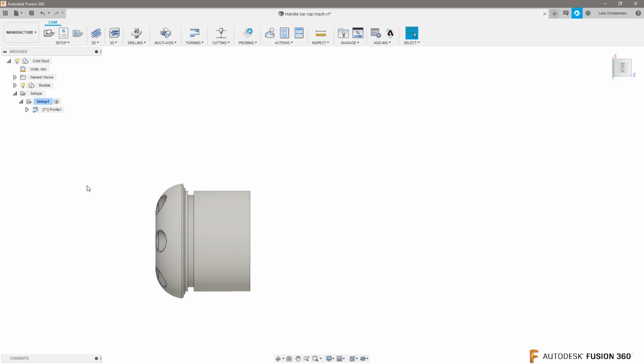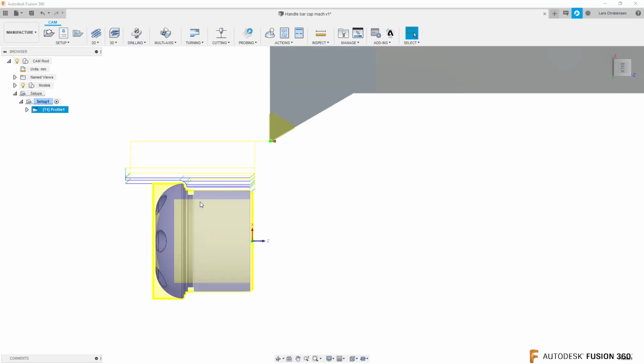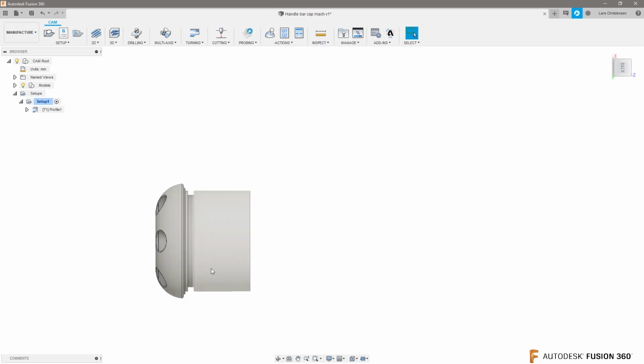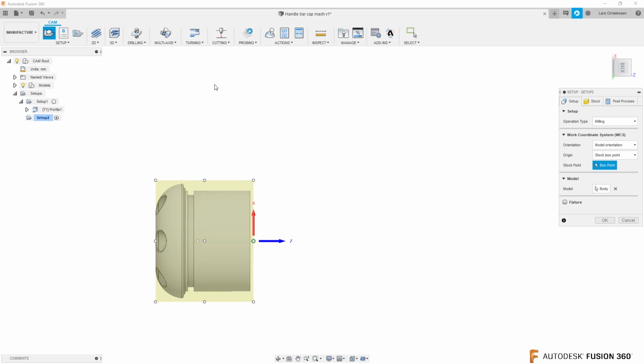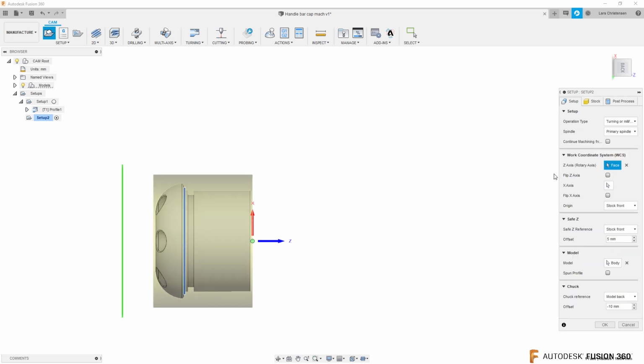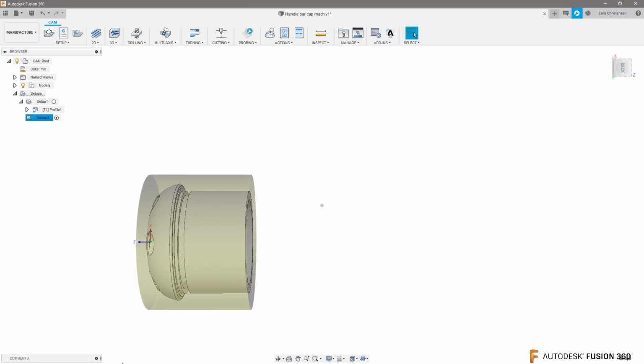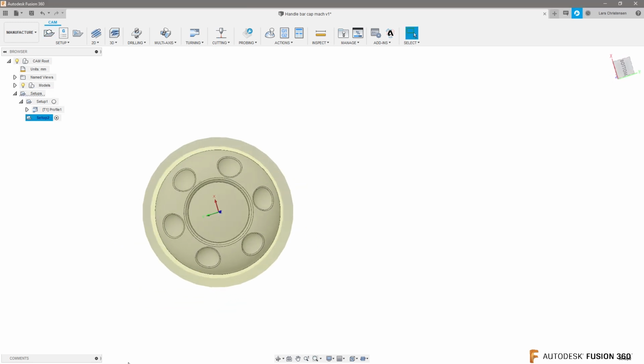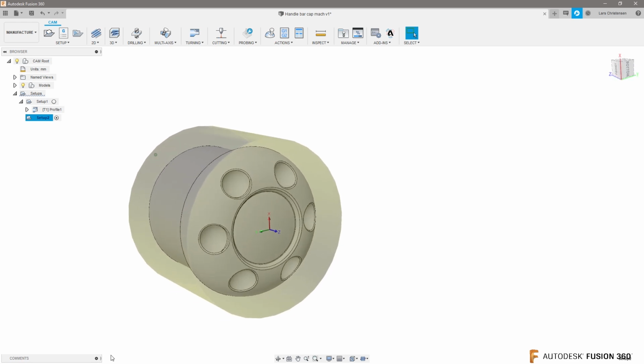The other thing I want to show in here, just because there's a chance that you get thrown up, is now we machined one side. Now we got to do the second side. I'm going to create the second setup. I'm going to change that back to mill turning like we did before and flip the axis. Now I'm literally having a second setup. Hit OK here. Okay. Now I'm going to show you something that you may or may not run into.